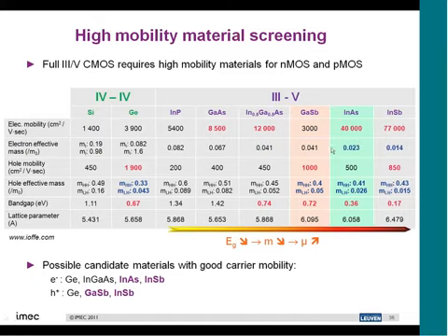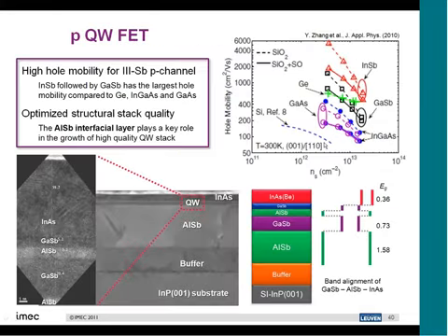So this gave us the idea to make a very interesting combination and actually use this 6.1 category of materials, as we call them, so materials with a lattice constant of 6.1 to make the next generation of devices. For example, this is how a 3,5 PFET quantum well device could look like. We start with, in this case, indium phosphide that we have grown the buffer on, aluminum antimonide, gallium antimonide, again aluminum antimonide buffer, and we make actually a contact layer in indium arsenide. So this shows the stack that we have been growing.